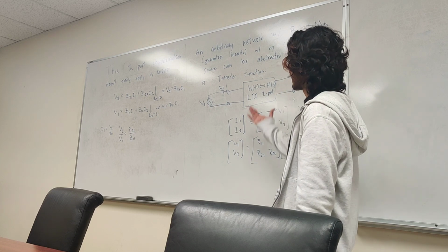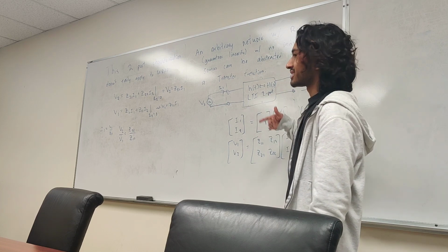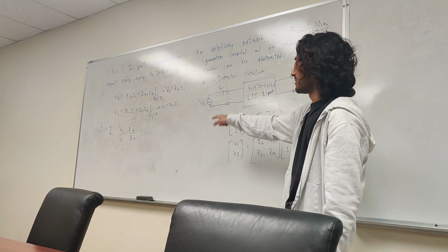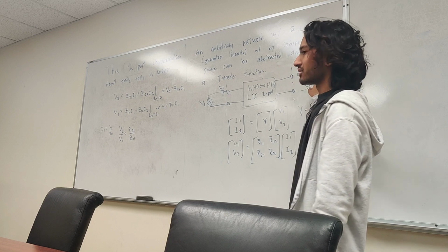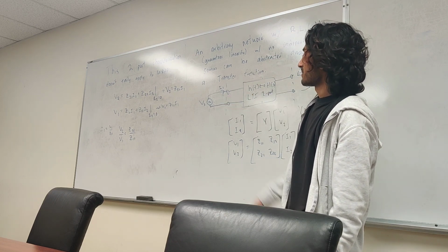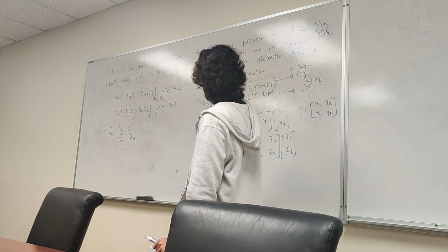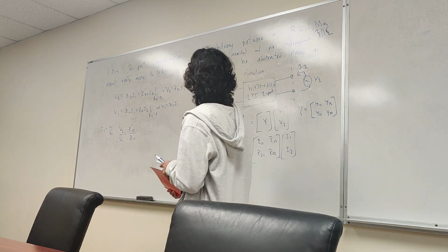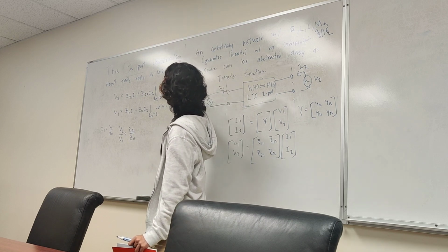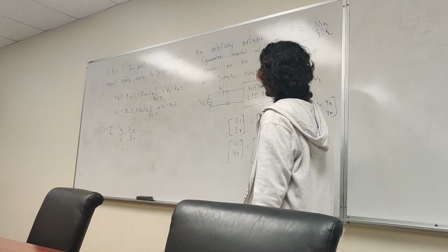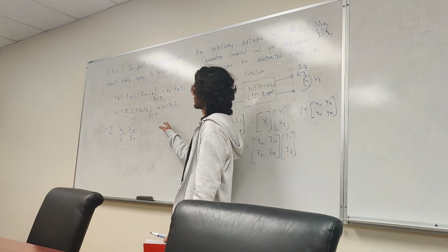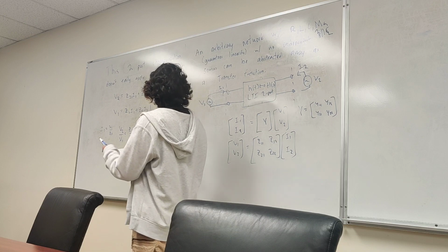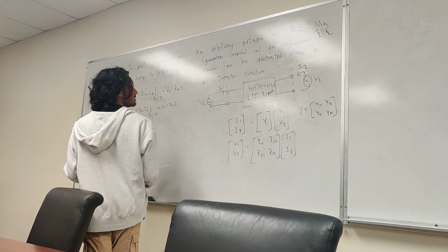So this is great. When we talk about putting these systems together, we talk about signal gain, signal loss, right? So we have a signal over here. We know Z21, we know Z11. We can figure out what V2 looks like. That's our gain. So it's kind of a handy number to remember, right? But calculating Z21 and Z11 is a little tricky. And these two core characterizations we've talked about, the Y and Z parameters, don't easily apply to RF. I'll show you in a second why. The math is not as easy as you may think. I'll show you a very simple example.